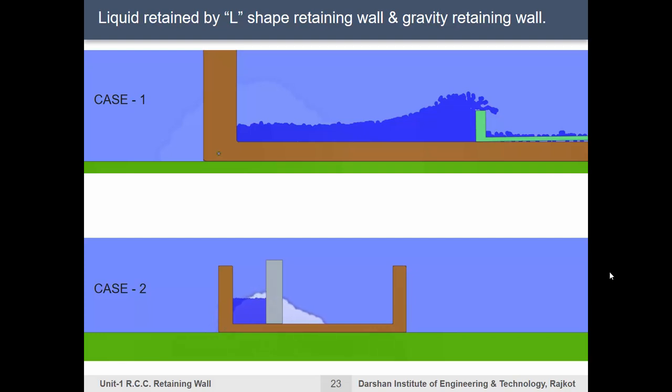With this slide, I want to develop the understanding that in liquid retaining structures, the weight of water on the projected leg does not help much in the stability of the dam. Rather, seepage, which occurs most of the time in dams, may be the prime reason for dam instability. Here, I would like to recall a way-back slide on water pressure coefficient K being unity. That is, water exerts the same pressure in all directions, whether vertical or horizontal.